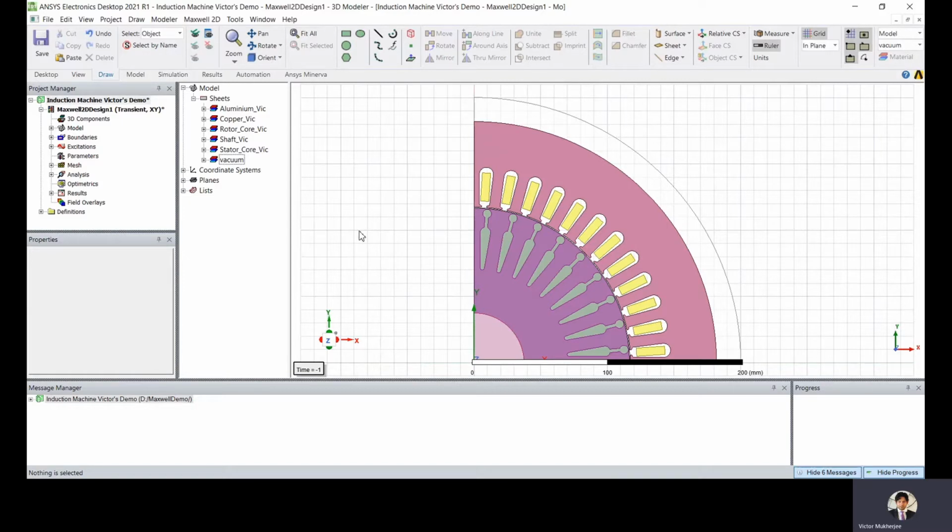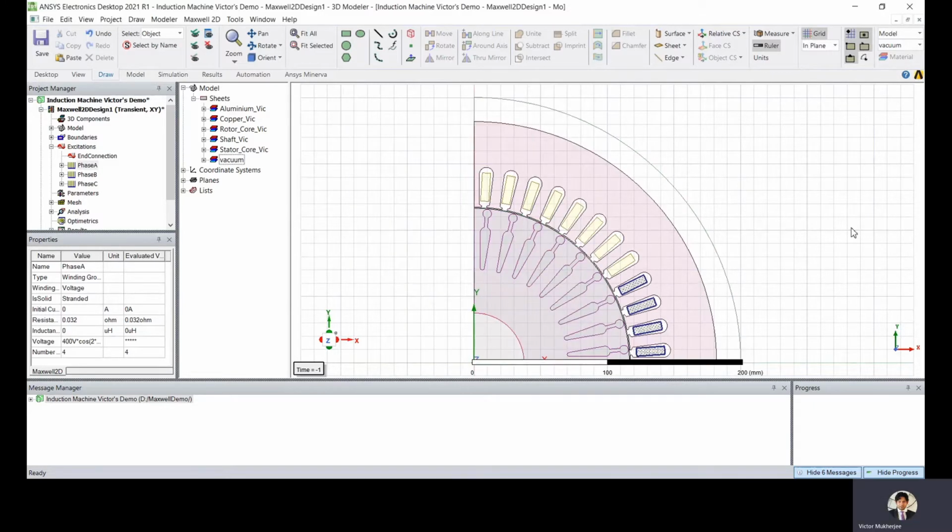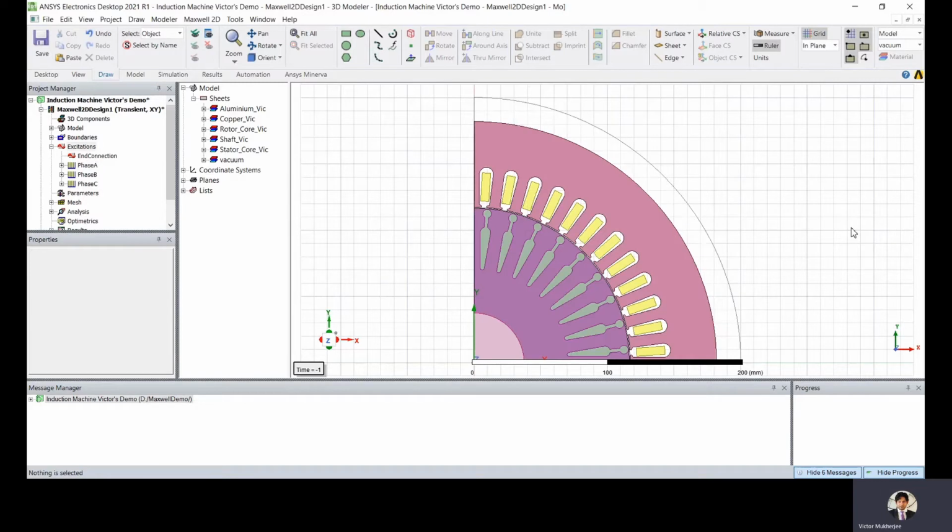Then if you do not know what the initial current is, there will be a huge transient current in the beginning. For example, if you give a voltage but you do not know the initial current, then whenever you simulate, you see a very high initial state of current, which takes a significant amount of time to stabilize. But we can smartly initialize the whole problem in a way that avoids that kind of transient in the beginning of the simulation.